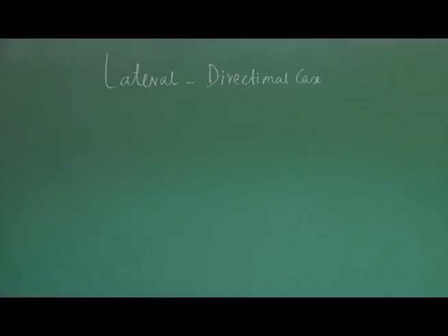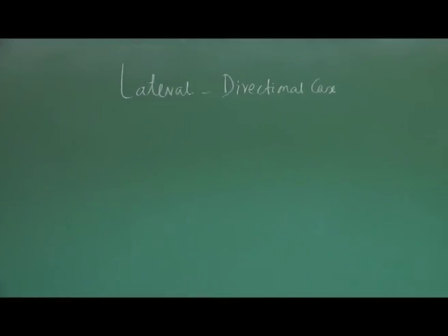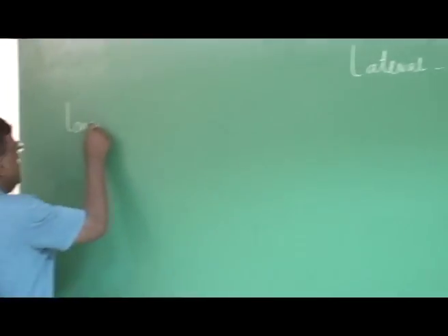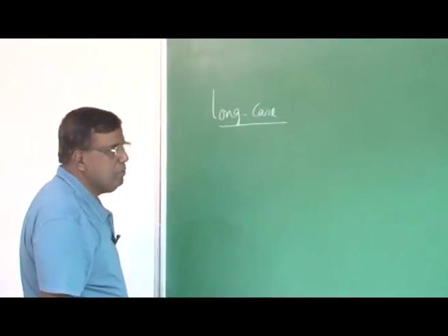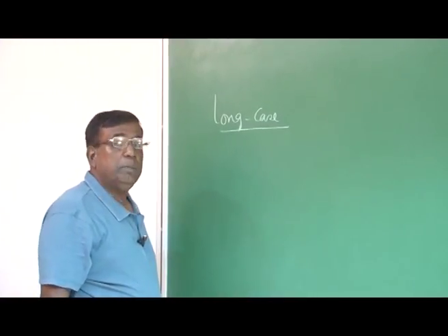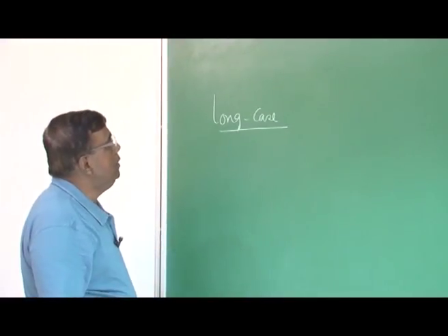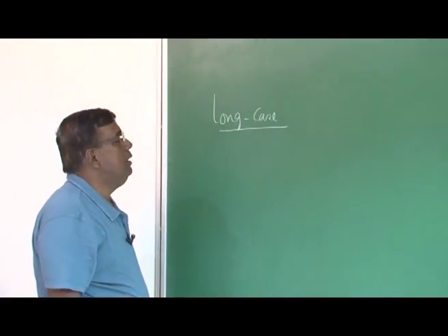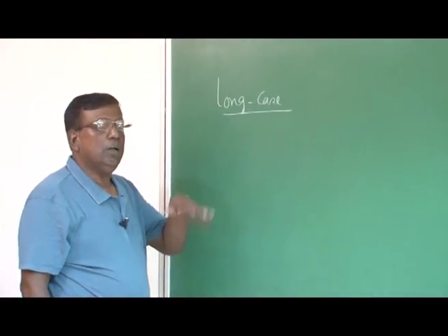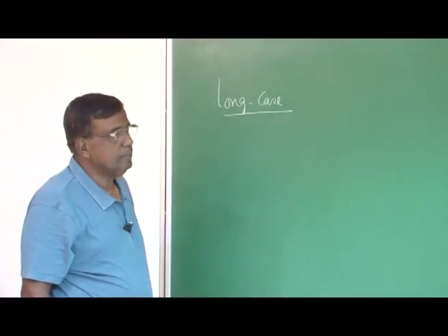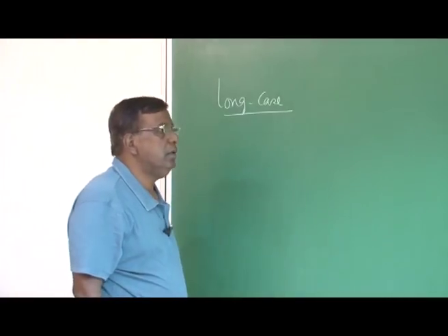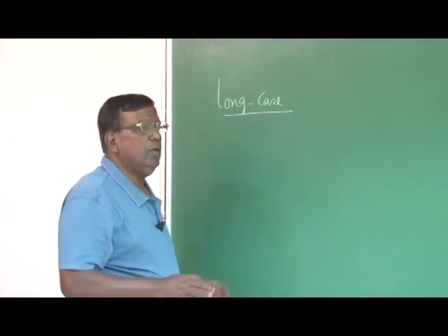Before we go to the lateral directional case, let me give some passing remark on the longitudinal case. Please understand that for the longitudinal case, we have assumed small angle and also the perturbations are small, and that helped us in decoupling longitudinal from lateral and directional case, right? But for high performance aircraft, things are a little more complicated.